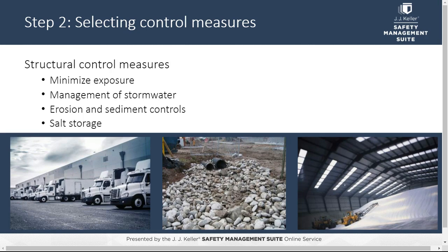Sediment control measures that trap eroded sediment should be the second preference and include installing structures such as silt fences and sediment ponds. And finally, if it applies to your activities, structural control measures including covers and enclosures should be implemented for de-icing salt piles.